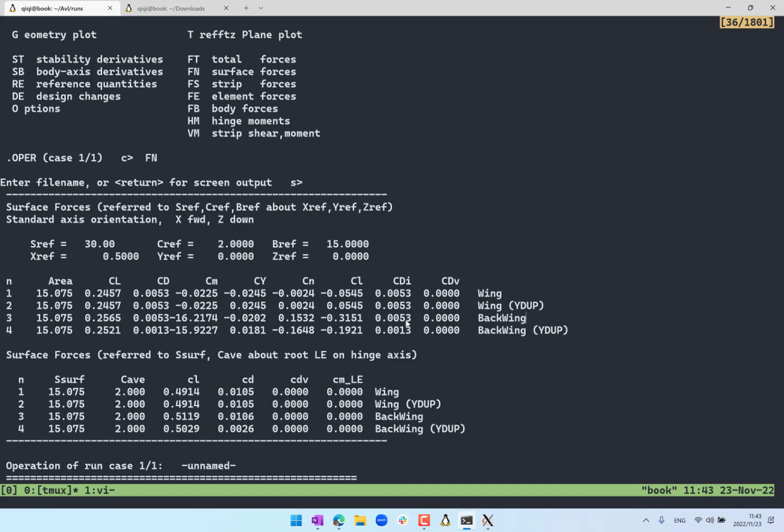So this would be a case where you would actually look at the total induced drag. Because of the way I'm deflecting the aileron, the wing closer to the trailing vortex of the front airplane actually gets less lift. That less lift decreases how strong a tip vortex that wingtip has, and combined with the lower lift, it further decreases how much induced drag it has. While the other wing, because it now has a higher lift and a stronger tip vortex, has its induced drag increase. But overall, you still get plenty of induced drag reduction from the whole system. All right. Good.